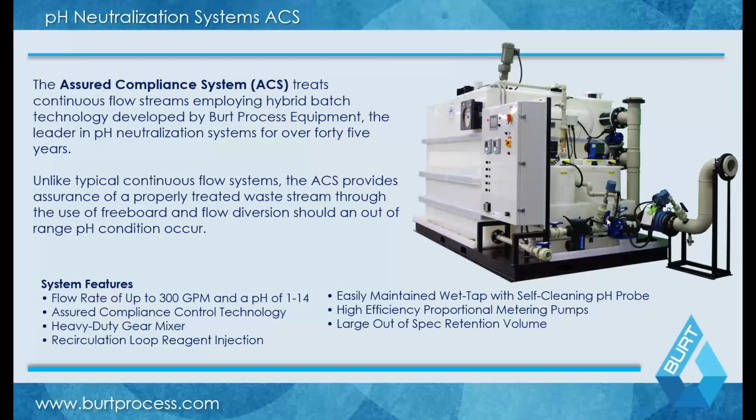They also have here a recirculation pump, as you can see, where you're doing your pH monitoring in the recirculation line. You're doing your chemical injection as well, and this allows you to use your waste as a carrier medium to allow a more rapid or more efficient chemical injection for better treatment. So this is how you can do it. As I said before, you can do more treatment in a single stage.